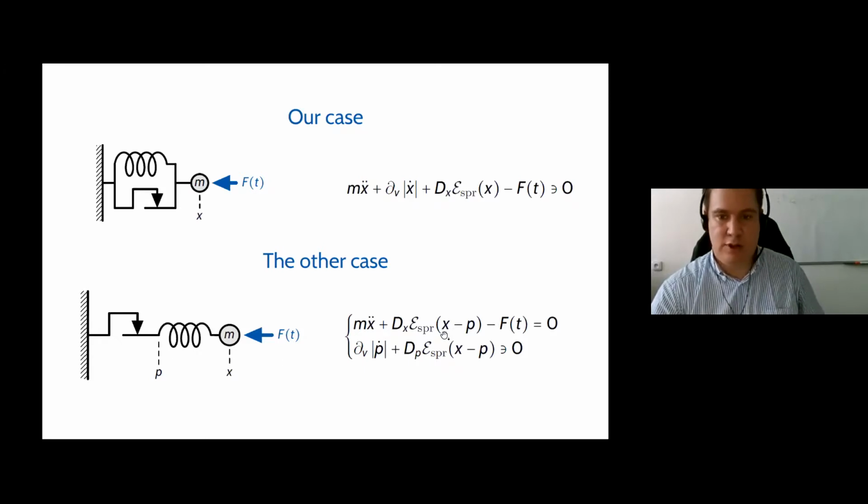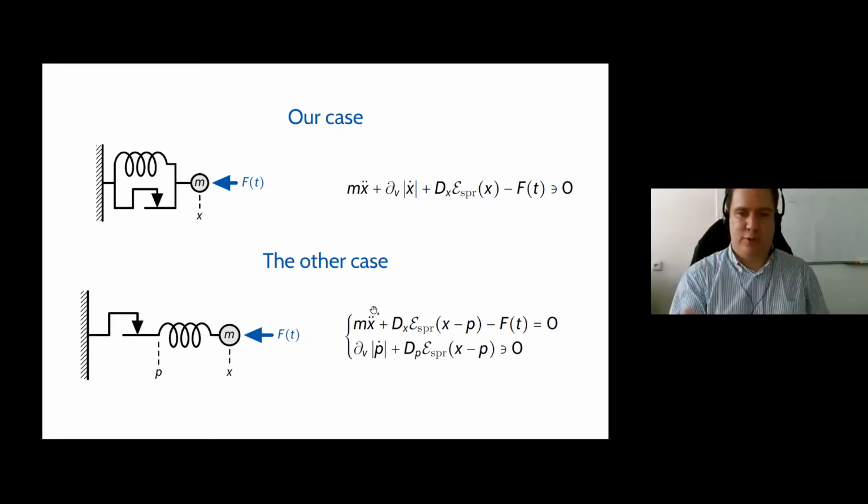So as you see, you have two equations, one variable less, and inertia never interacts with friction directly. I don't say it is easier or more difficult, it is qualitatively different. And something similar also happens if you consider continuous models for crawlers. If you look at a continuous crawler, so a strip of an elastic active material, you get that M is no longer invertible.